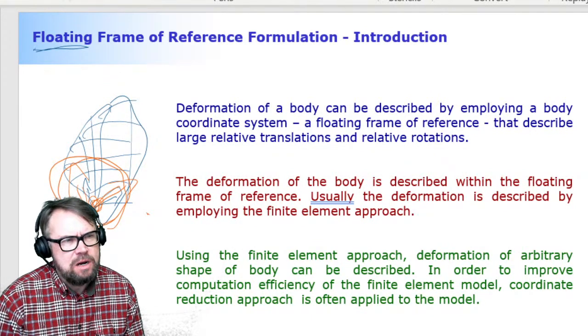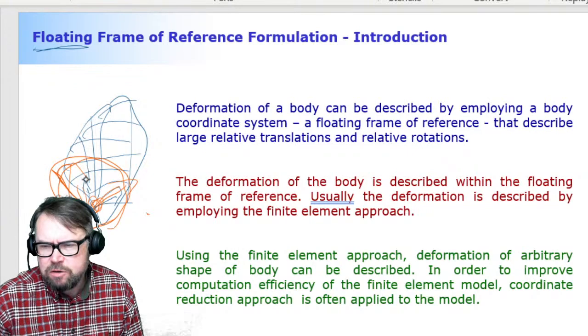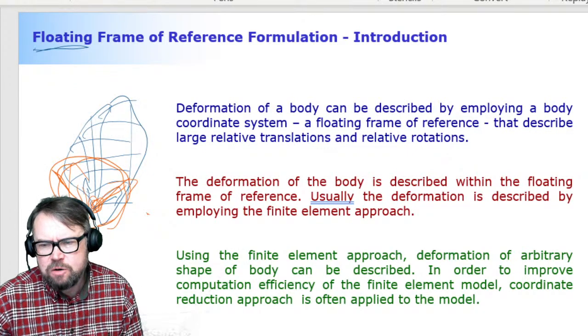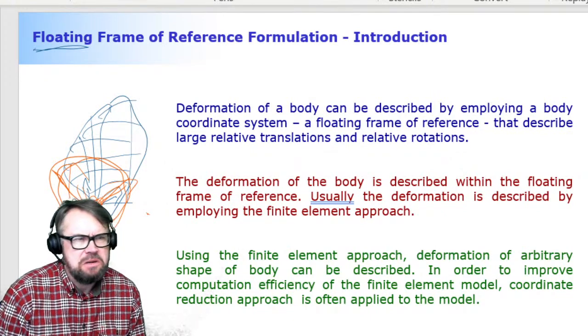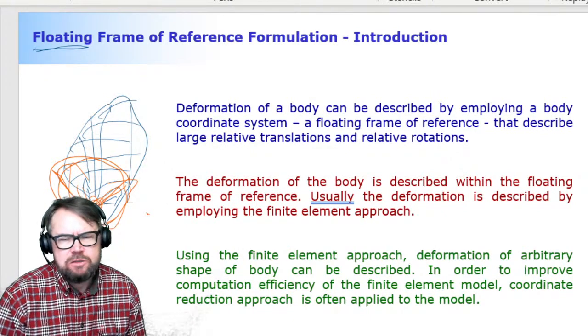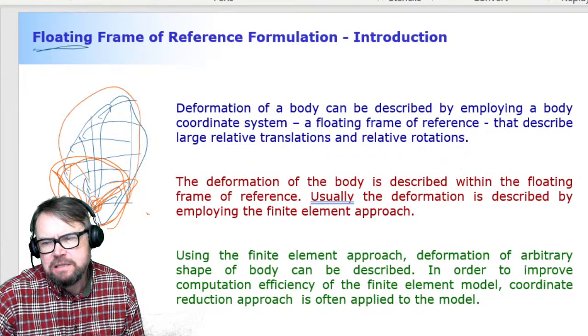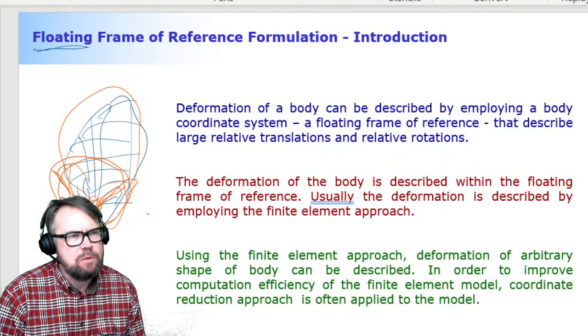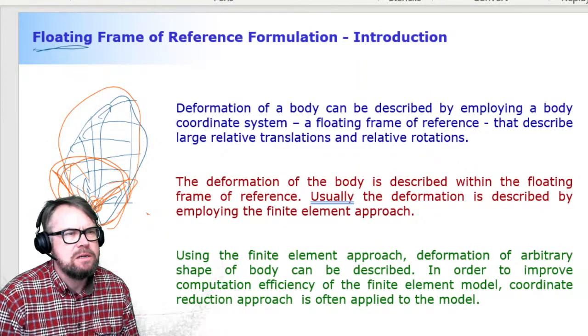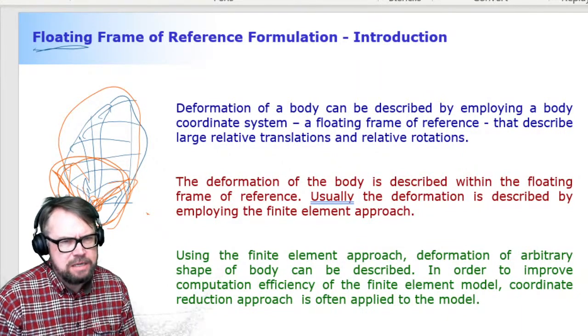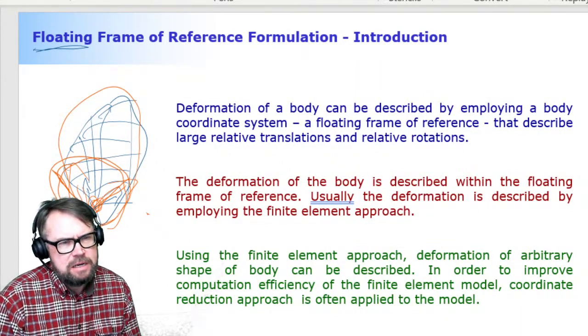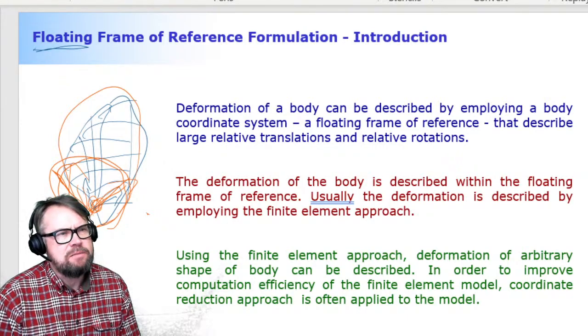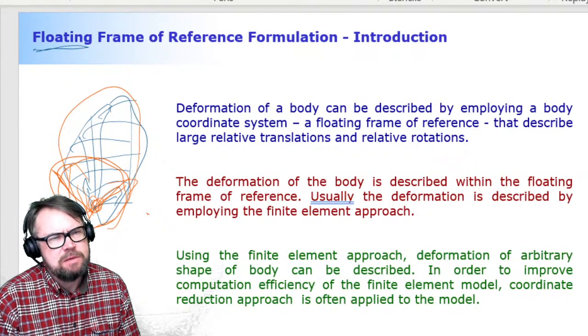And that is described with respect to this reference coordinate system, which needs 6 coordinates. Not good. They don't match. So we need to do something about that finite element model. And something that we can do for that is model reduction. That's where we need to look at the vibration, and we need to identify the properties of this finite element model.